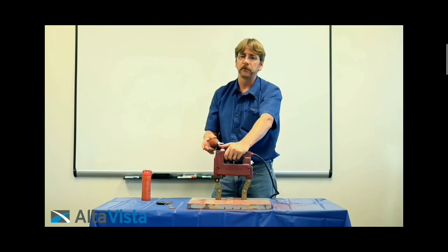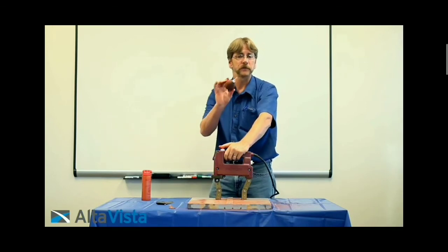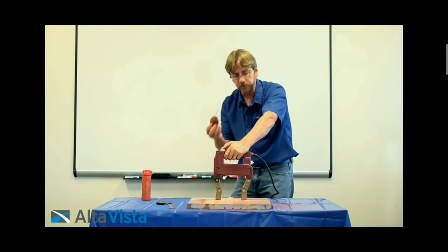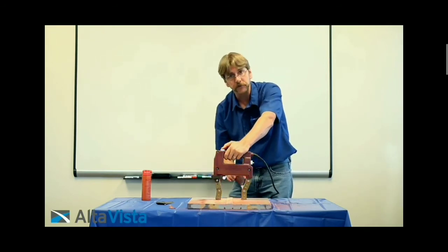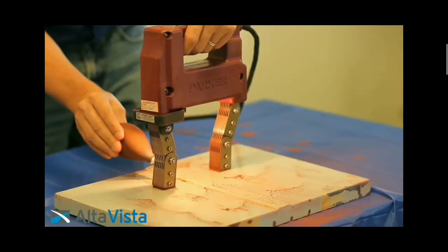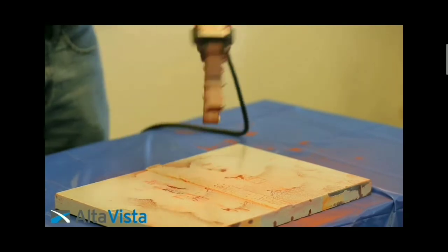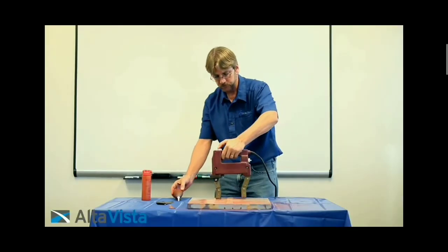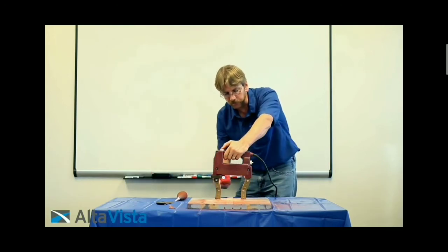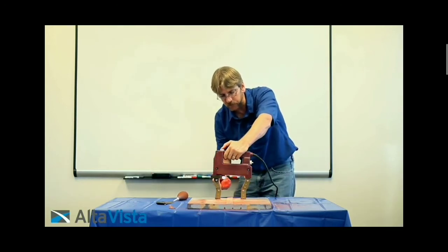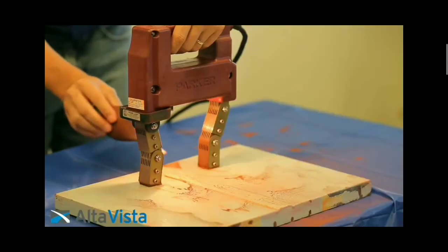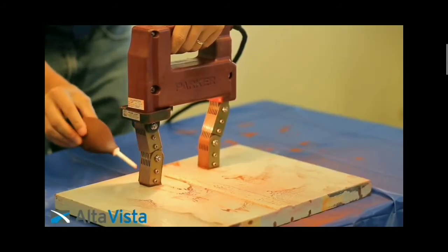As I talked about before, it's important to know the proper technique of blowing the particles off, because if I use too much force, especially on a painted plate as opposed to an unpainted plate, I can actually blow the particles away and you no longer see the crack. So again, it's important to have the proper technique in floating the particles on and watching them form, and also the proper particle removal with the blower.